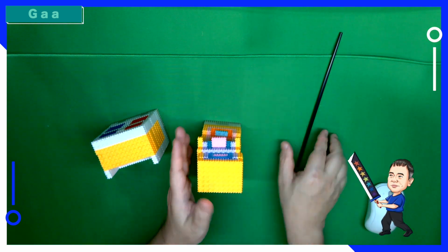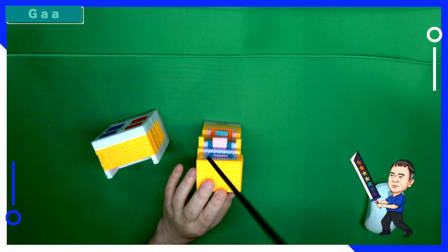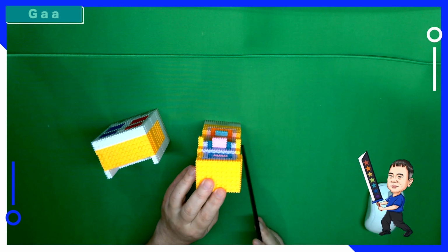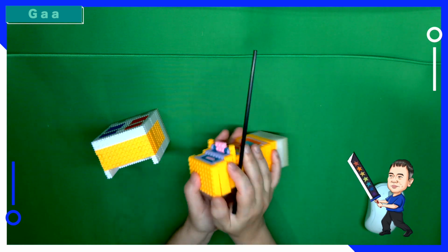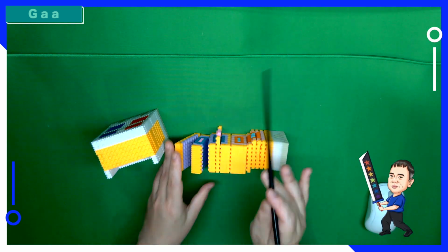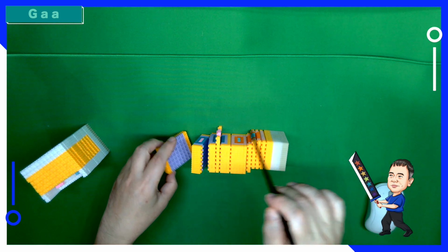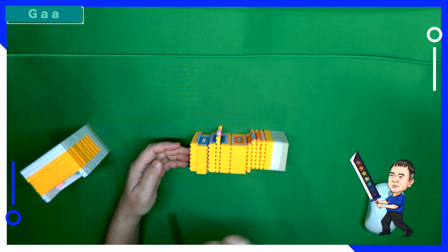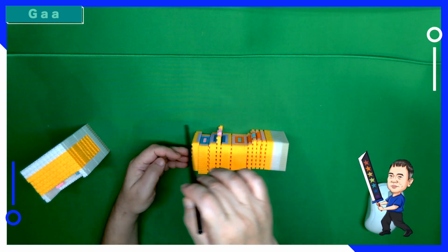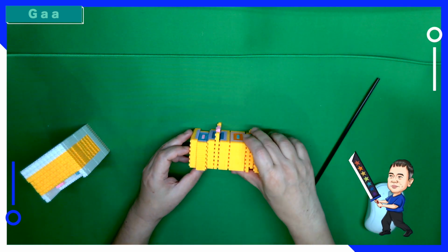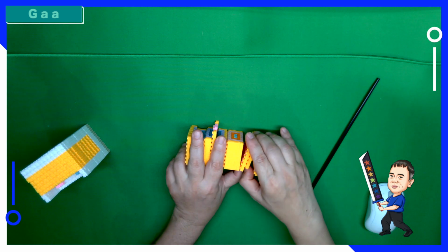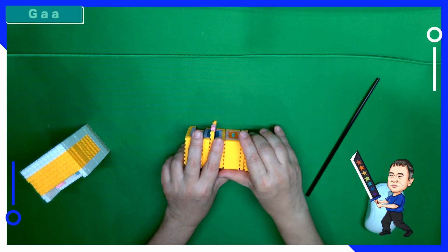Because all the connections come from the top, the N channel down here has a longer conducting loop, so it is given higher conductivity. The P channel has a smaller one. That way they can have a similar current for different conducting loops.